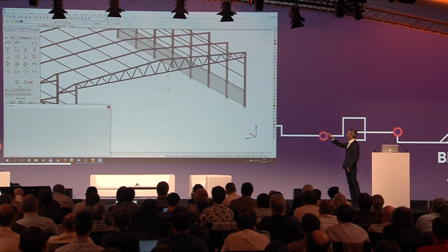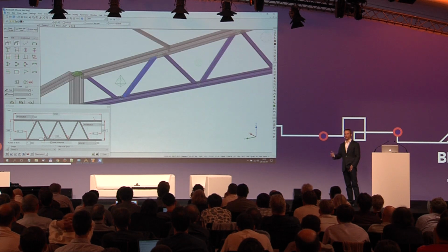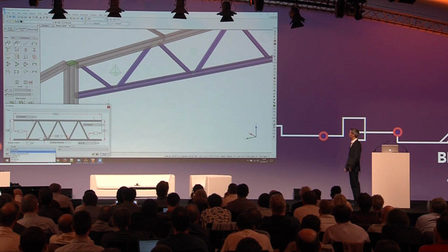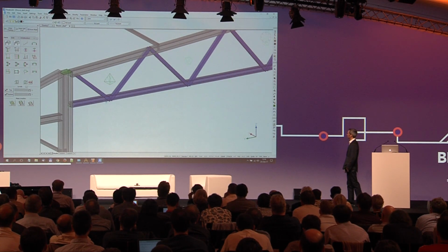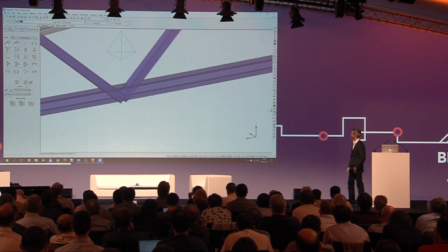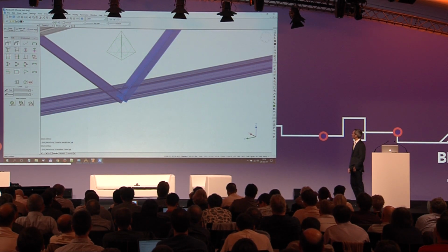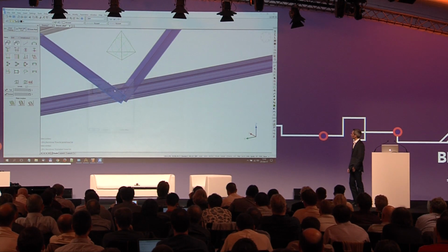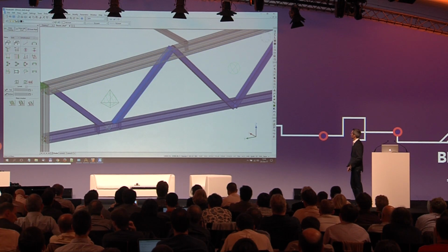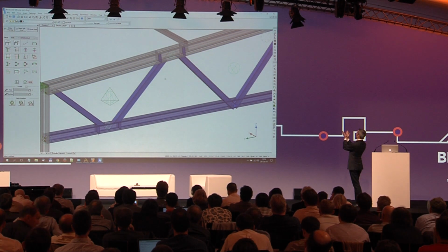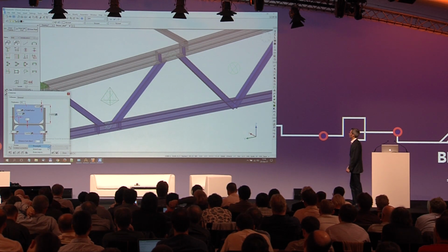So these have simple welded connections right now, which we will remove and replace with something more complex, for which we will also use the library and find something with stiffeners. So you can see that these V-shapes, they're all a little different in angle. The higher it goes, the closer the V-shape.